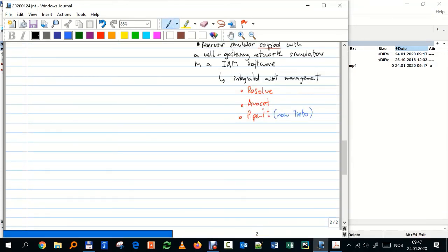Other options I can use to estimate production profiles. Material balance. But usually material balance is not enough. I have to have what I call an IPR equation, inflow performance relationship. Material balance tells me how pressure and saturations of gas, oil, and water are going to change versus time, depending on how much I'm draining from that volume. That's what material balance is.